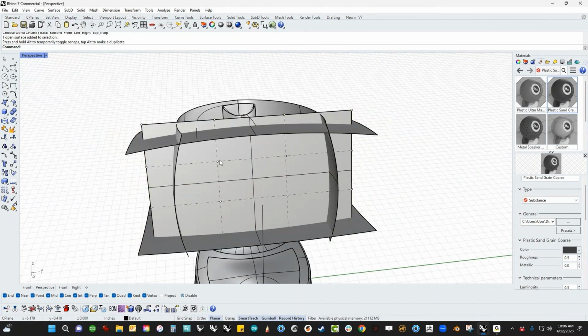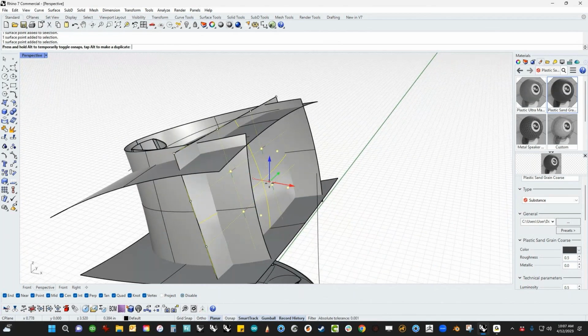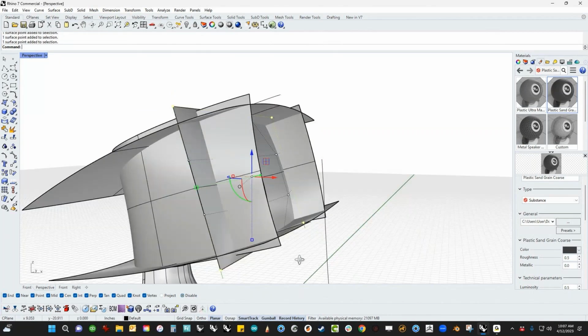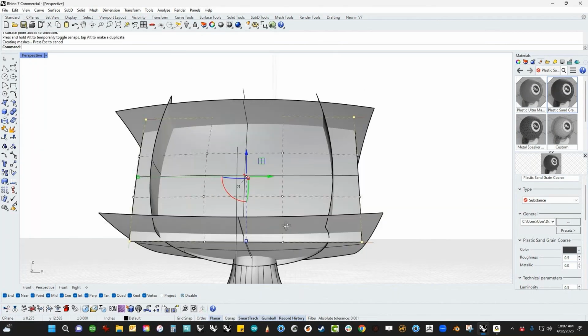And then I'm going to add some crown, which all I need to do to add crown is just grab these 4 points. Just pull them. Just going to add the tiniest bit of crown to that. And then the second part of that trick is to grab these 4 points and just pull those back a little bit. And you end up with a really beautifully crowned surface.